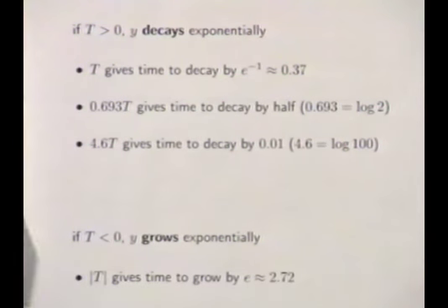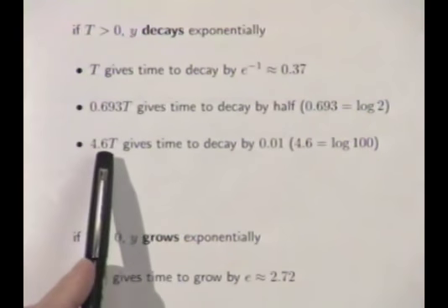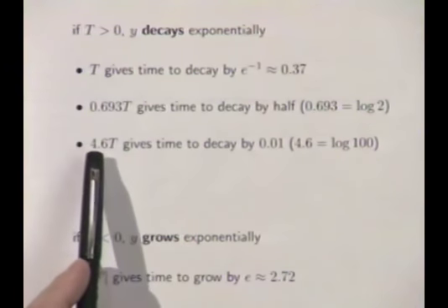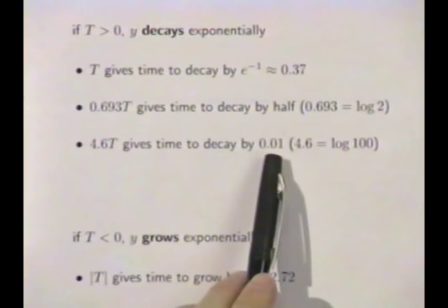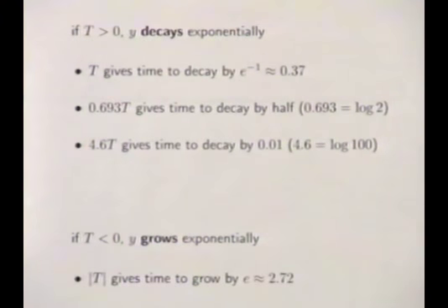It's the doubling rate or the half rate, half-life, they call it sometimes, all sorts of things. Now 4.6 T, or in casual conversation, 5 T, 5 time constants, is the time it takes to decay to 1%. So the time it takes for an exponentially decaying signal to become indiscernible to the eye on a plot is about 5 time constants, which you know from 101.